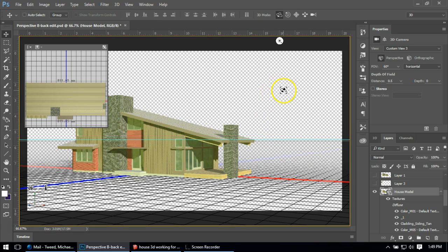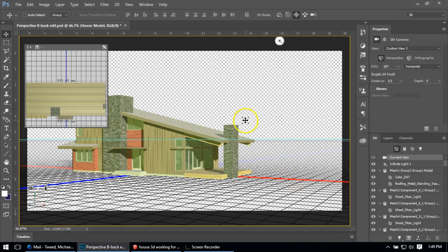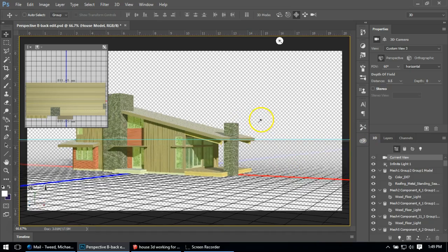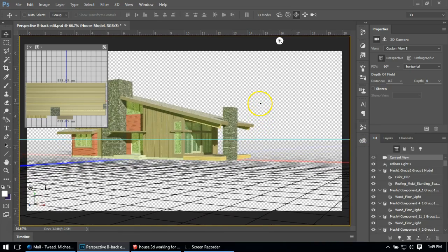The next step: once I've got my field of view and the horizon line set, I'm going to go back to the move the view button, and go back to 3D so I can see what I'm doing. I'm going to move my drawing up, because I need to make sure the part of my building that is about eye height is also aligned with my horizon view, because I'm doing an at eye level photograph, so that's going to be the key.